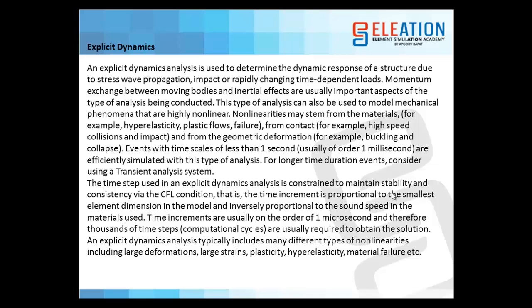So in dynamic analysis we majorly see the stresses and deformation because of the force which is changing with respect to time. So we are actually seeing the values of stresses and deformation which are changing with respect to time, which is quite logical. Momentum exchange between the moving bodies and inertial effects are usually important aspects of the types of analysis being conducted.